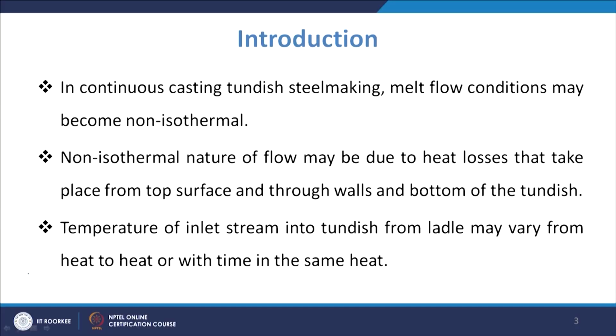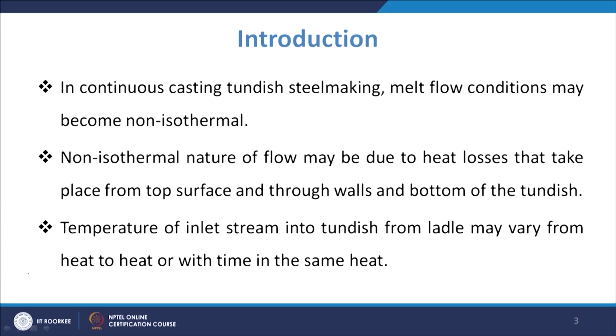So, in continuous casting Tundish steelmaking, many a time your conditions may become non-isothermal, because the temperature may not remain constant. This non-isothermal nature of the flow may be due to the heat losses taking place from the top surface, through the walls, and through the bottom.